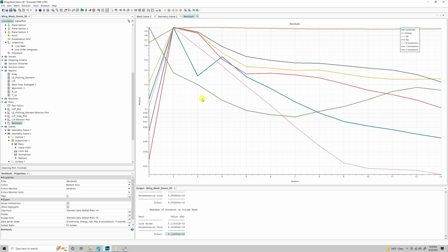If you're having a problem and your simulation is crashing, might be due to a bad mesh, might be due to a bad boundary condition, could be any number of things. But you don't know why. It should be working. Why isn't it? Happens all the time. Because again, you're never going to be able to get everything exactly just so for any realistically complex simulation. You're going to be able to get it close, but you might have problems in corners and not know about it. And it's crashing. You need to fix that. Obviously, you need your simulation running. But we can find out where there's a problem.